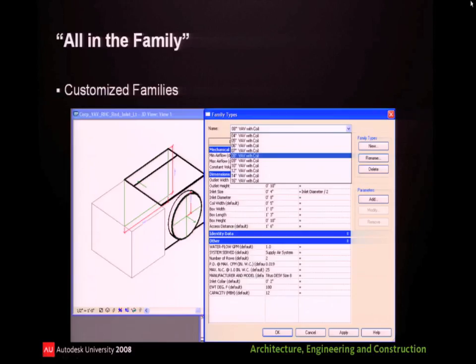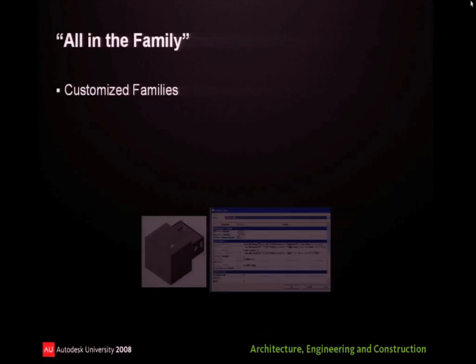This box you see out here, grab my pointer, this box out here is basically a clash detection for the control box. We can modify that 18 inches, 3 foot, whatever we need to make sure that space is respected in the model. That was our first generation. It took a while to get there with Revit systems.